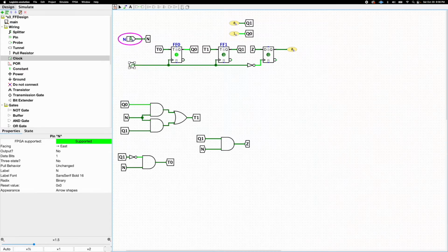So if we go ahead and add 1 again, we're going to be at our second nickel here. And if I cycle once through the clock, we're going to be here in state C. And we're already getting a gumball outputted here, so that must mean we're at 15 cents. And if I cycle through, we'll just go back to the very beginning here. So let's go back to the beginning state here and reset everything. So now that is how this circuit works.